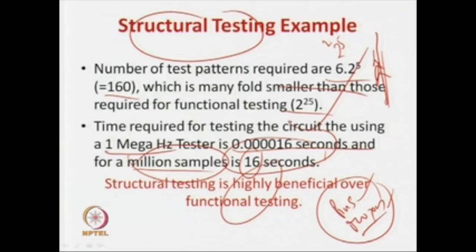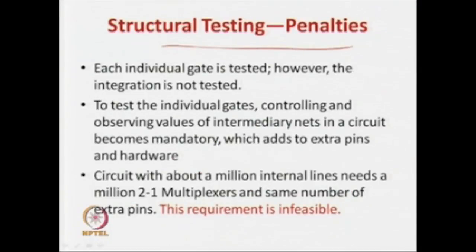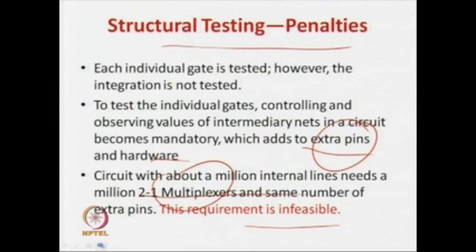So, research has been done, which we will study in this course, and we will see something in today's lecture also, on how pins and multiplexers can be brought down. That is feasible, but still taking the test frequency higher and going for functional testing is a difficult problem. So, that is the structural testing penalty which we have discussed. You require extra pinouts and some multiplexers, and these requirements are directly infeasible. So, you cannot have that high requirement. So, let us see how we can handle the problem of extra pinouts and extra multiplexers.